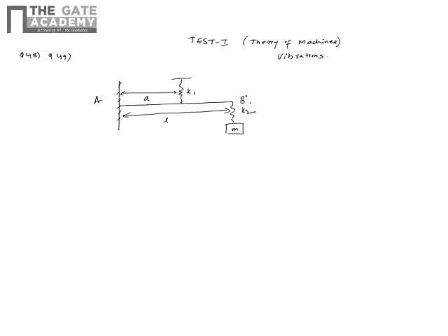So now we'll go step by step. Now AB is assumed to be rigid, so AB doesn't deflect on its own. So the only expansion that can happen is in the springs. For the first bit we are asked to find how much point B has deflected. Because of this weight, there will be a downward force on point B, but when point B tries to move downwards, this spring will try to expand, thereby creating an upward force which will try to balance the rod.